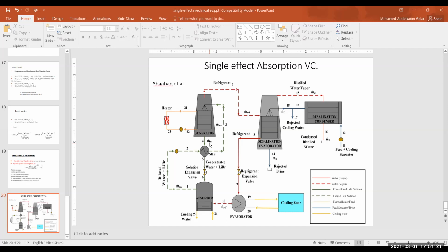So why is that? Because we are using a compressor, and the compressor is compressing vapor, and the vapor usually has high specific volume. You know that for steady state, steady flow processes, the work is given by the specific volume multiplied by delta P. If the specific volume is high, then you are talking about substantially high energy needed to run the unit. It's not like pumping water. The specific volume for water is 0.001, so it's a small value. When you multiply that by delta pressure, the total power for the pump is not high. But not for a compressor, because simply the specific volume of the vapor is high.